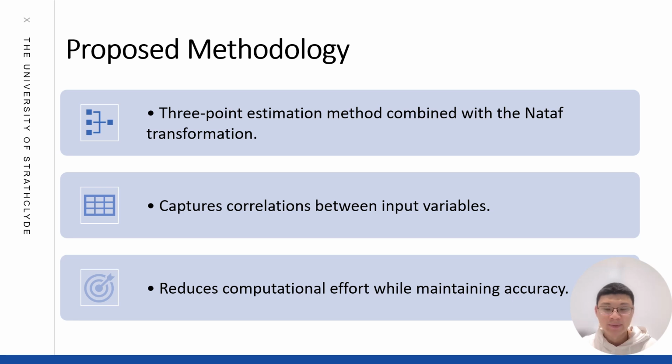The three-point estimation method provides an efficient approach to calculating stochastic power flow by estimating key statistical moments of input variables. It reduces computational complexity by using three strategically chosen points to approximate the distribution of each input variable. These three points, typically representing the mean and the two deviations, enable efficient estimation of output parameters without the need for exhaustive sampling as required in Monte Carlo simulations.